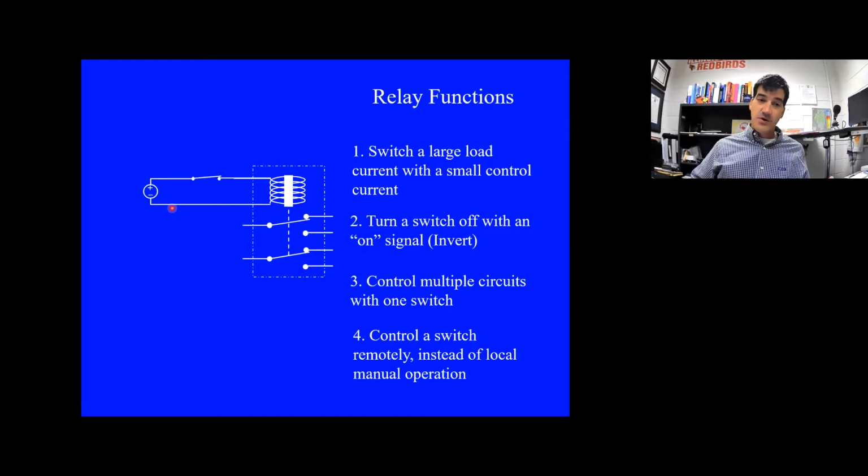So there is no way that you're going to be able to power a sizable motor with the output from an Arduino or a Raspberry Pi or any type of computer. A motor is going to take way higher voltage and, importantly, way more current than a little computer can provide.